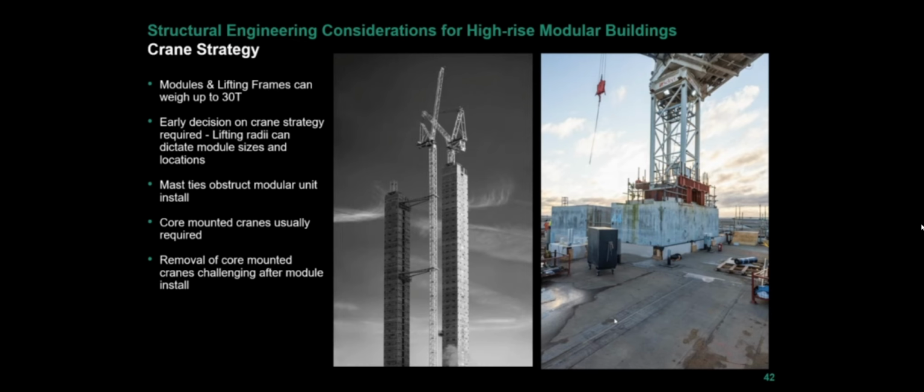So they're quite big. Luffing cranes are required, which require fairly significant steelwork and post-tensioned cast-in high tensile bars into the core. It always needs to be designed and coordinated, and those tie-in bars need to be coordinated with the module connections and various other items as well to make sure the whole thing works. That all needs to be done at an early stage.